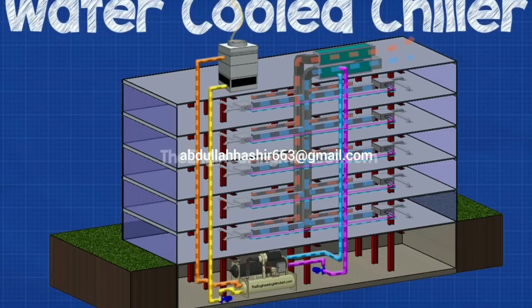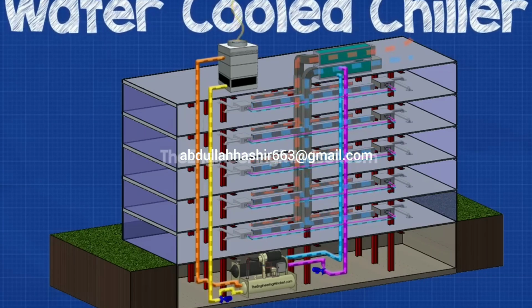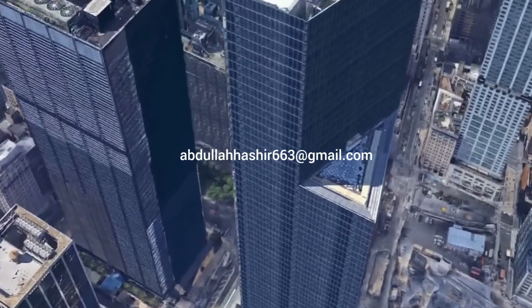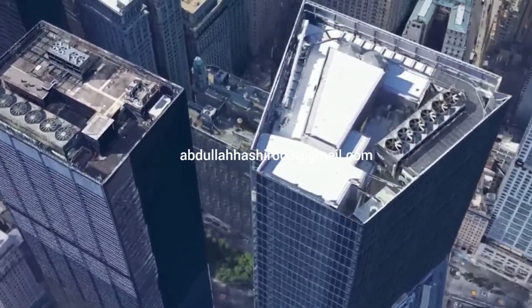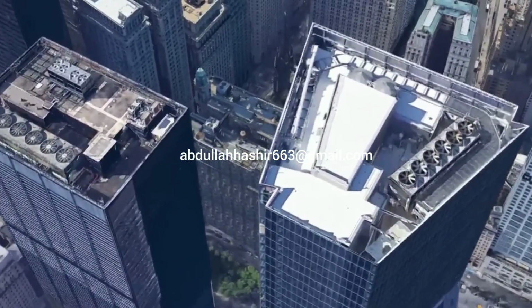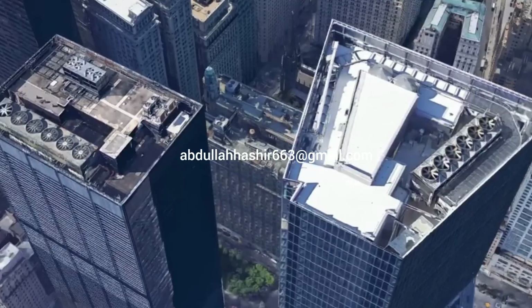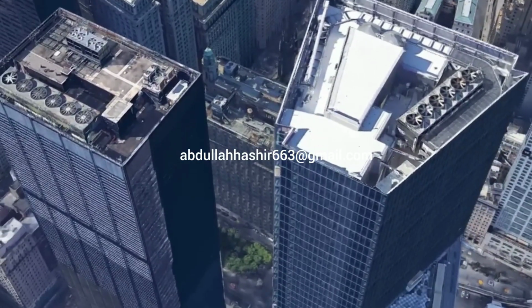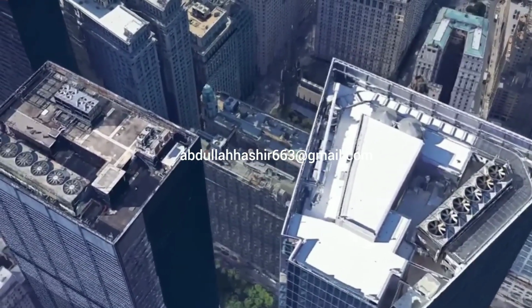So in this instance, the condenser of the chiller has been cooled by water, so it is now a water-cooled chiller. Water-cooled chillers are typically used on large commercial properties with high cooling loads. You can tell if a building has a water-cooled chiller because it will need a cooling tower, which is typically located on the roof. There will usually be more than one chiller and cooling tower, and it's not uncommon to have at least 2 or 3, even more, just for redundancy as well as variations in cooling demand.